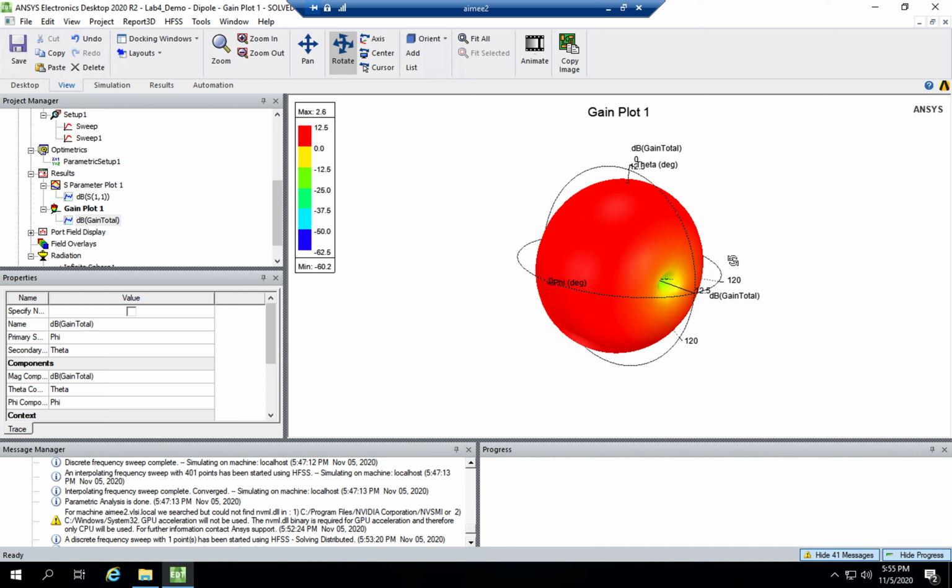As you guys may have known, we do have two types of gain. We have a copolarized gain and a cross-polarized gain. So the copolarized gain is, of course, the gain which is along the polarization of the dipole. So this would be along the y. The cross-polarized is the one that technically should not radiate because it's perpendicular to the polarization of the dipole. And this type of radiation pattern does not tell us this information. So that's one thing we're missing in this case.